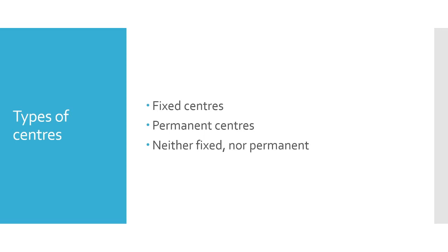So what is a fixed instantaneous center? A fixed instantaneous center is actually a fixed center. If a point is fixed, that is a fixed instantaneous center. In the case of a 4-bar mechanism, we have a fixed link. That means we have two fixed points. Those two are fixed centers. Why is it a fixed center? The point is fixed and not moving. Fixed means not moving, or we can say it is permanent and not moving. Clear?